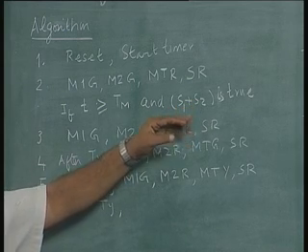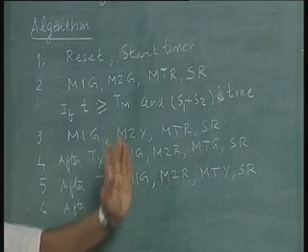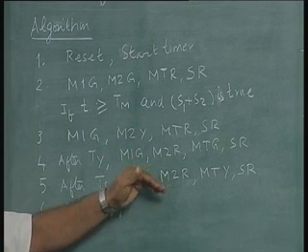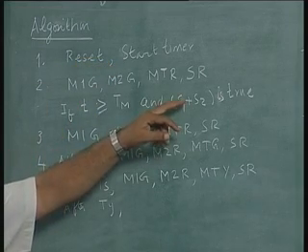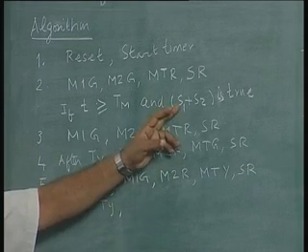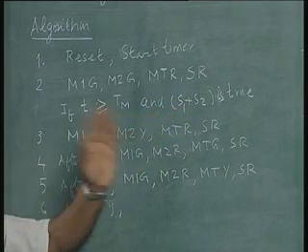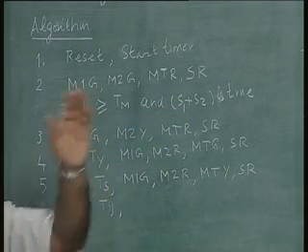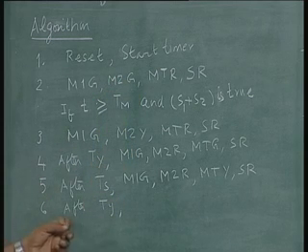So we do not have to spend time to give the green signal for turning from the side road to the main road, we can return to the main sequence. On the other hand, if S2 happens to be 1, either because of that or because both S1 and S2 were on, we would like to service the side road turning into the main road before we return to the main loop. So that has to be tested here.